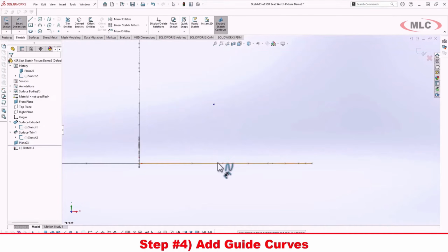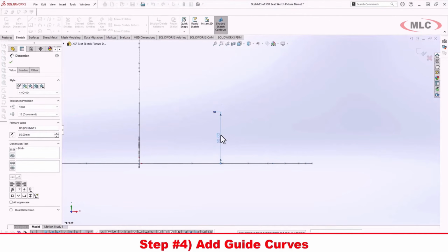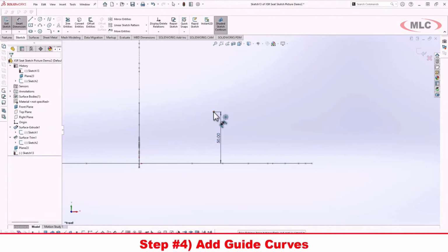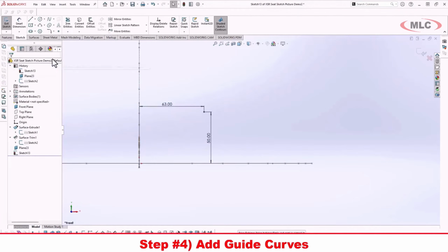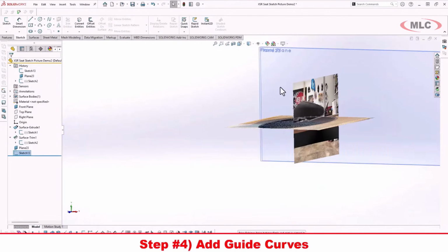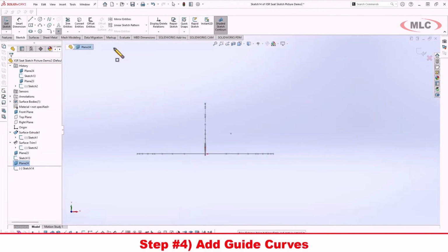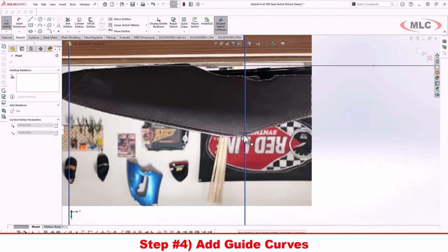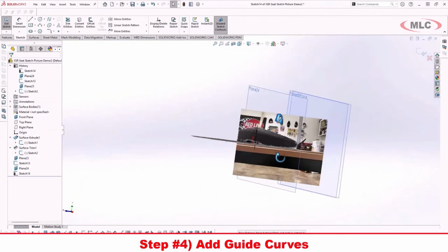The picture got me pretty close, but again, I don't think my angle was perfect. So an alternative, and probably better, option here is using a third sketch picture and a third angle to help dial in those guide curves. But I went ahead and kept working with this process, and I repeated the same thing for the point up front, got it set up, and don't mind some of the crazy camera work here.